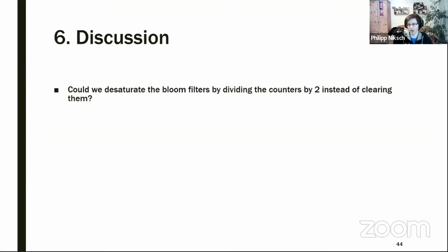You would probably have to be very precise on how much you subtract and how often you subtract in order to not allow someone to hammer a row just below this threshold, so that it gets subtracted enough so it doesn't actually blacklist the row.